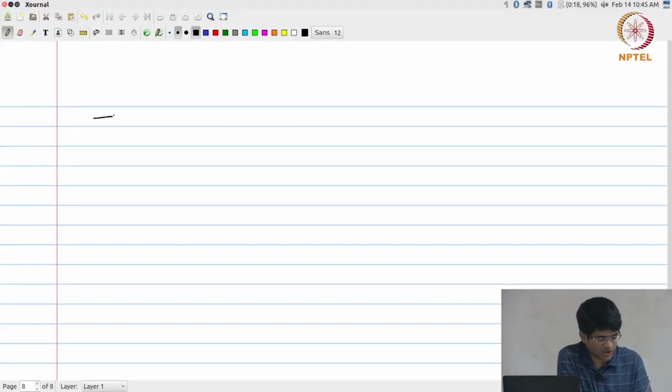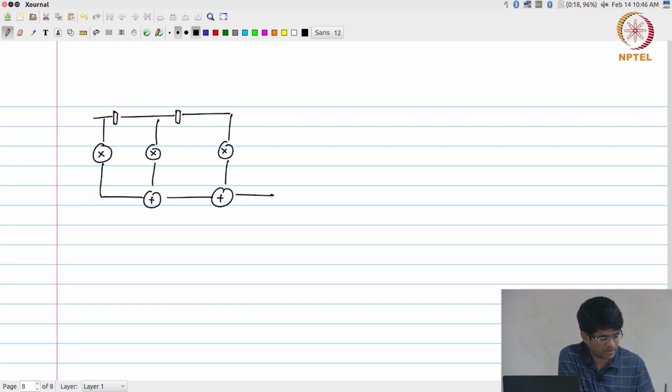Going back to the context of something like this FIR filter, what it means is that with this as my original diagram, if I wanted to have some kind of a division that allowed me to say, okay, everything to the left is going to work on sample number 1 and everything to the right is going to work on sample number 2, what I actually need to do is to be able to take my entire circuit and divide it cleanly into left and right.